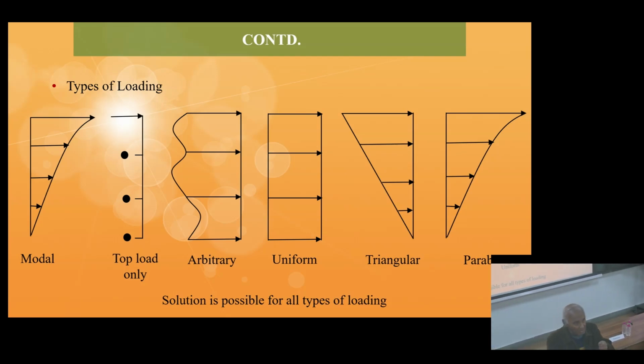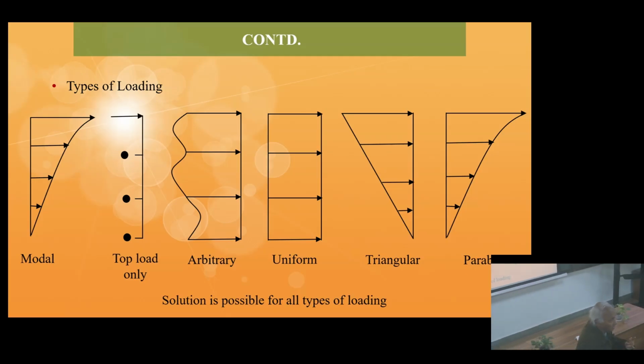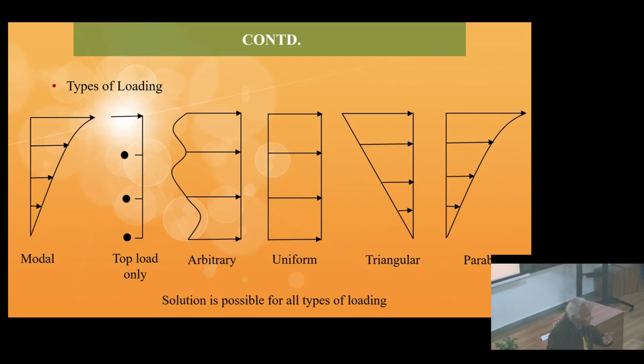Okay. And if I pull a structure and let it go, then it vibrates in its fundamental frequency, on the natural frequency, which is the least of the three. If it is a 3-degree freedom system, then out of the three frequencies that it can have, the least frequency will be that if I pull it and let it go, it will vibrate in the fundamental frequency.